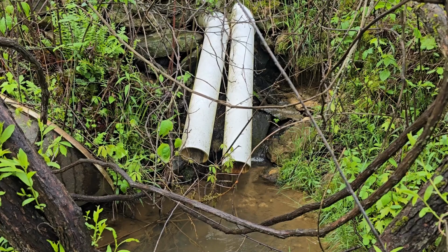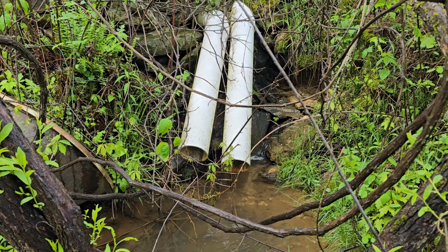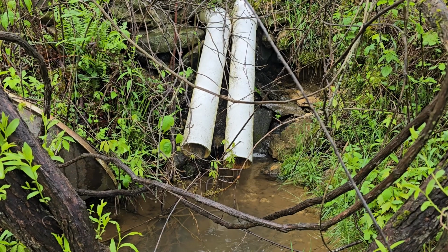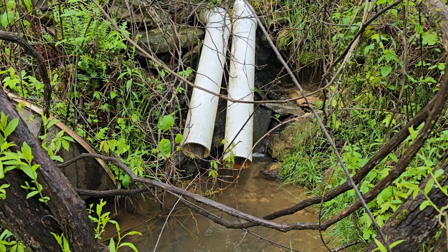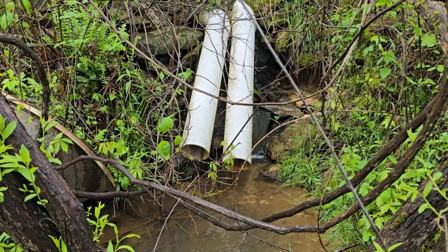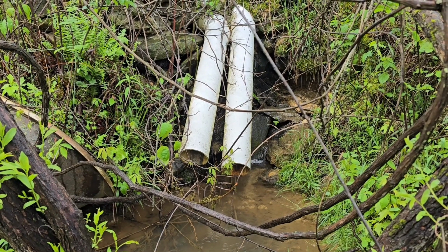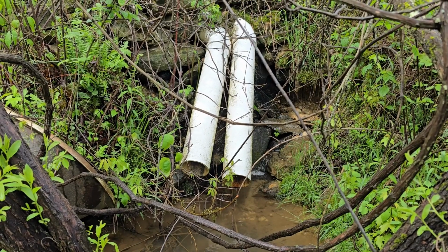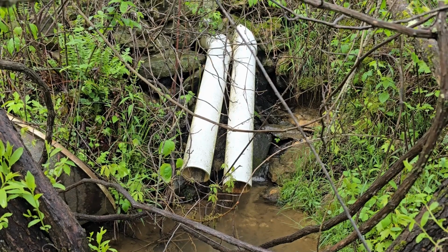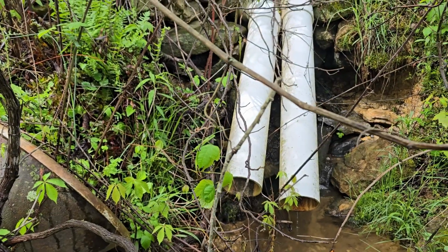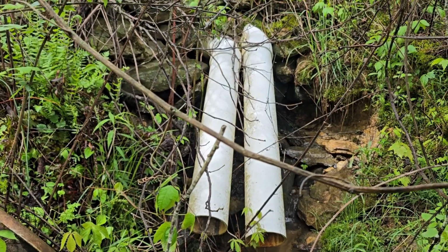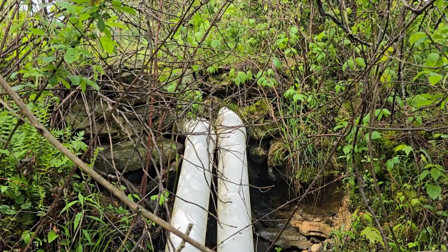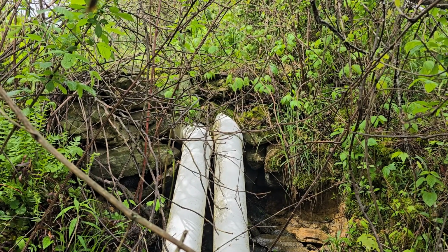Walking to the back side of the dam, I could see where each overflow pipe was turned downward using 45-degree elbows. No water was flowing in the pipes. It looked like the pipes had been installed where a spillway had been made with rock at one time. The original spillway was armored with rock, much like a waterfall, and did not involve the use of pipes. The water flowing over the dam had formed a 4-foot-high head cut in the spillway. I suspect that someone had installed the 2 overflow pipes because they did not want to rebuild the rock spillway.